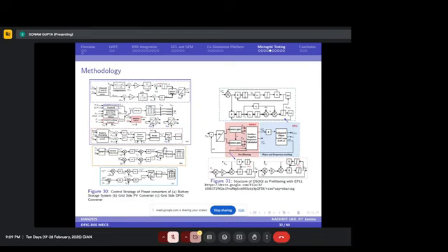So the main control structure that we have implemented here is on the PLL side, because the main concern here is how we ensure synchronization, or error-free phase estimation, so that the transition from the grid-connected to the islanded mode of operation will be smooth.